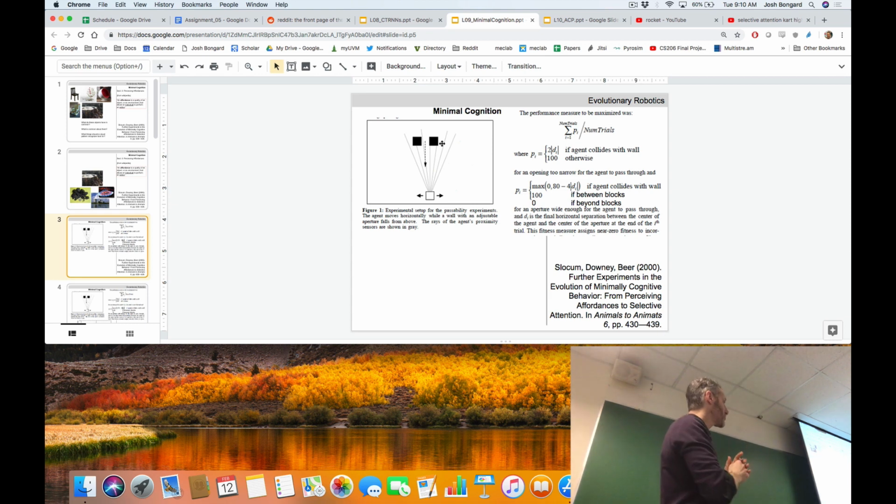So the robot has to evolve the ability to sense the width of that gap relative to itself and decide, quote unquote, decide whether or not to attempt passage between them. Okay, two rockets, and as you can see with these gray beams here, the robot is equipped with 7 ray sensors or distance sensors emanating from its front. And at every time step, it's getting back 7 floating point values that represent the length of these beams.